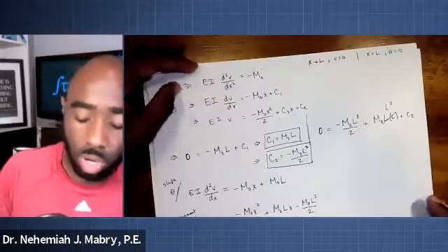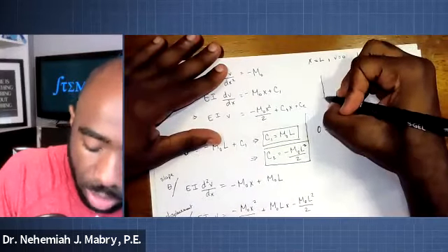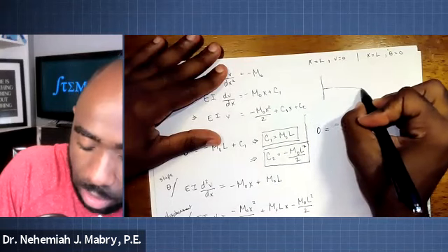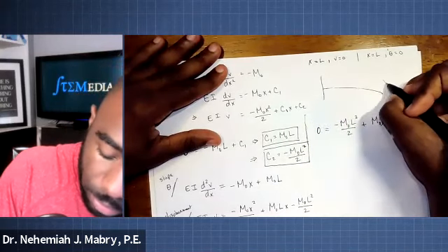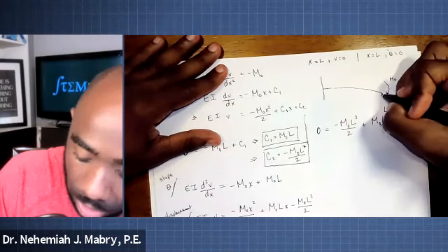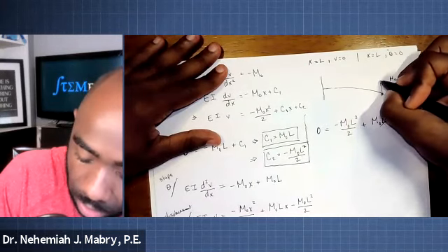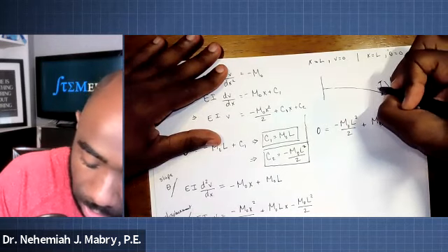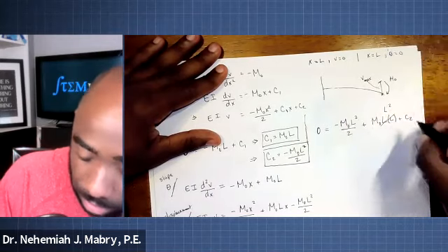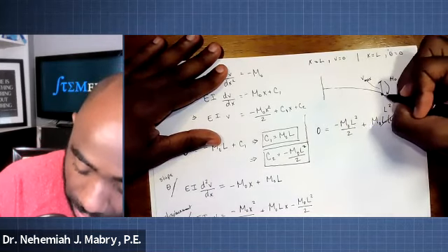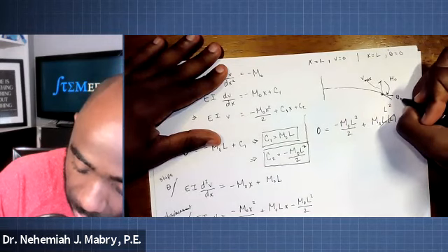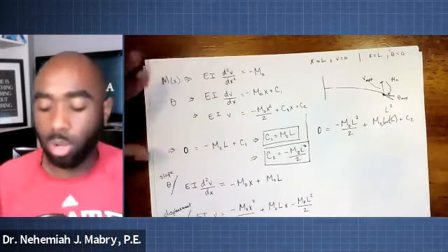Because if you were to draw the exaggerated shape as our play-by-play designates, this would look something like this because of that moment. And so now you would have, from its original location, maximum displacement, and then the angle of the tangent line will be the maximum slope.